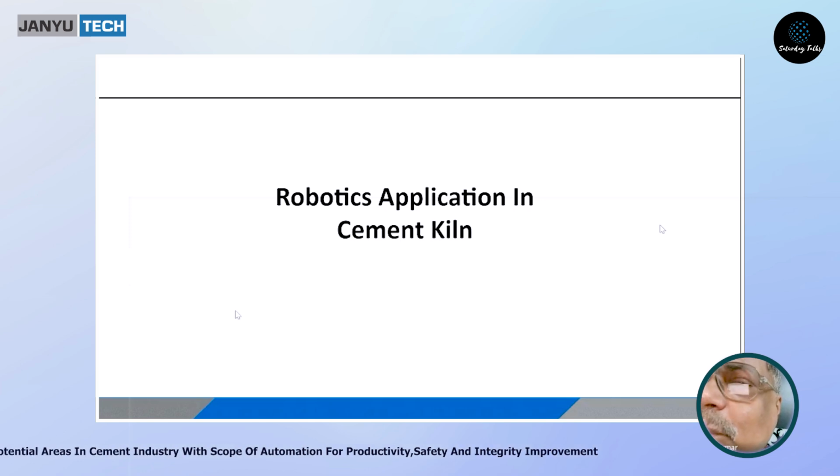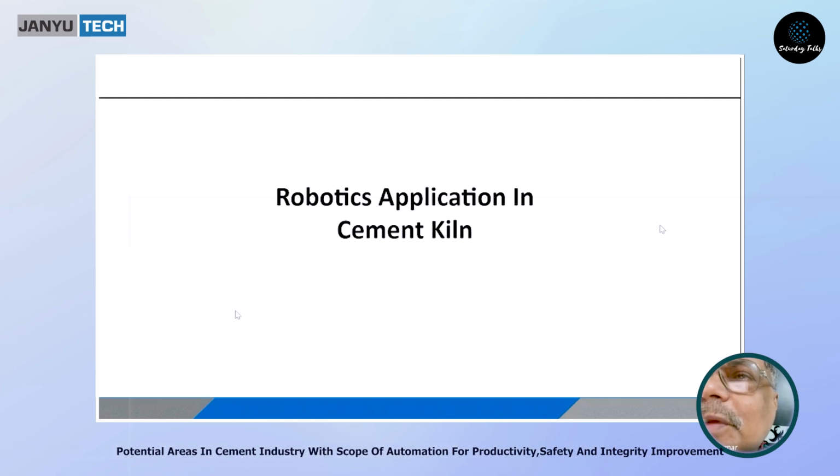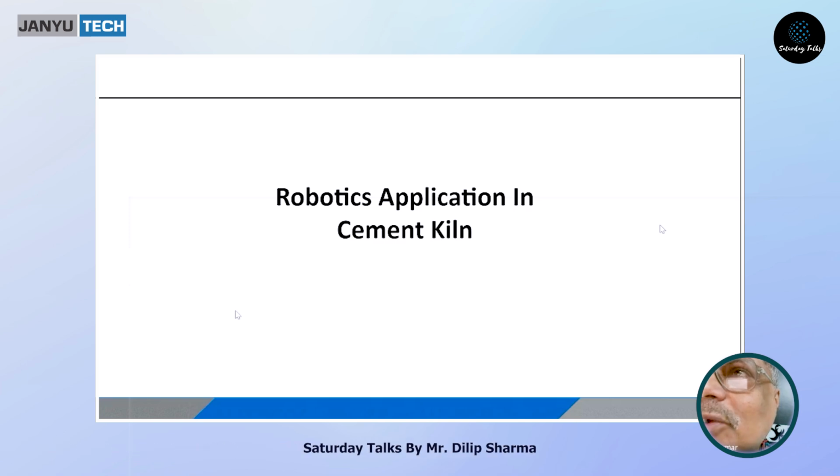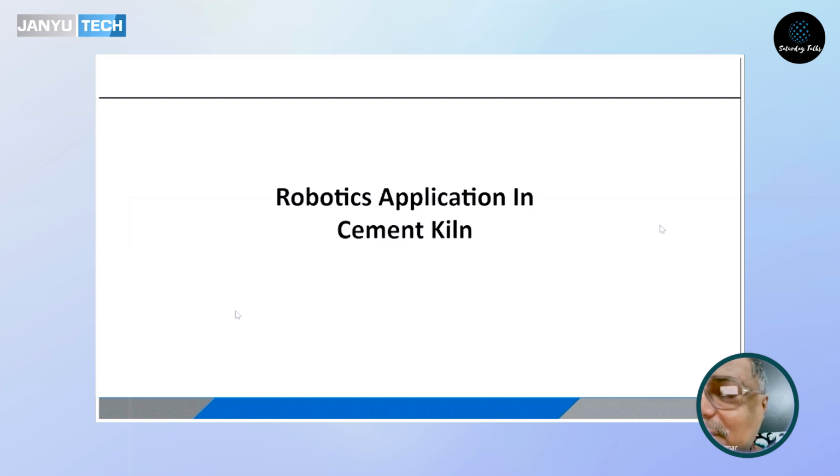In India, most of our cement manufacturers produce OPC, that is ordinary Portland cement, and in the entire eastern region, it is slag cement. And in Europe, they produce cement on ASTM or BS standard, where they are adding almost 40% limestone into the cement, which in India we are not permitted to do. So, because limestone is present in that cement, the chances of clogging are very less.